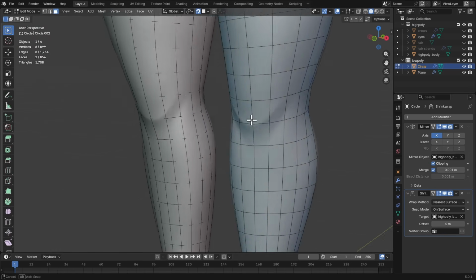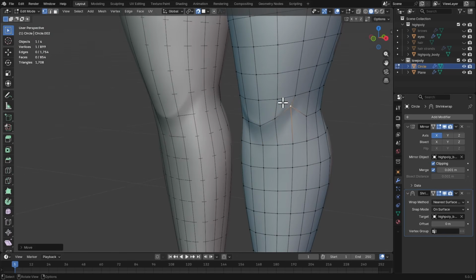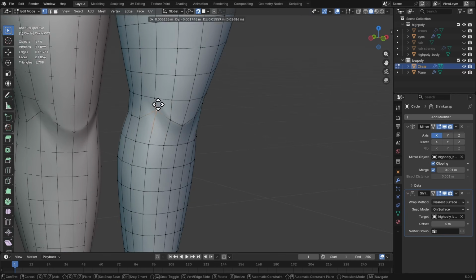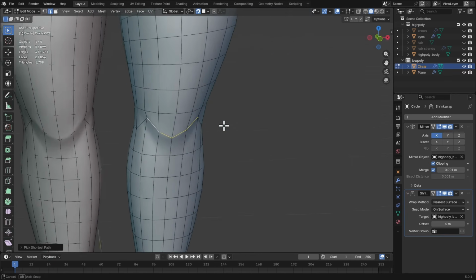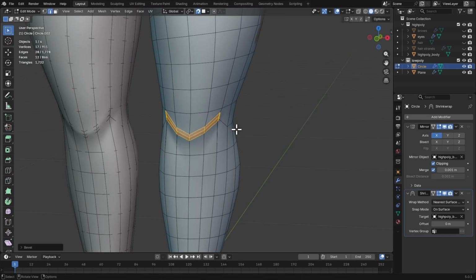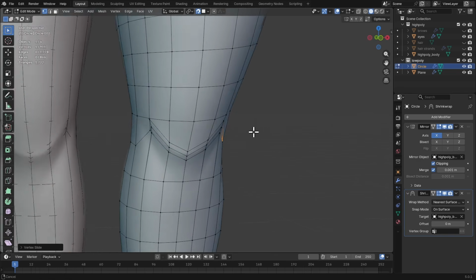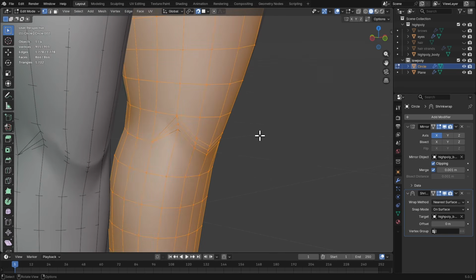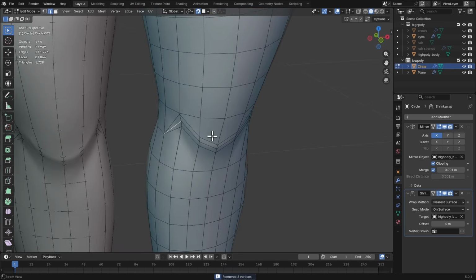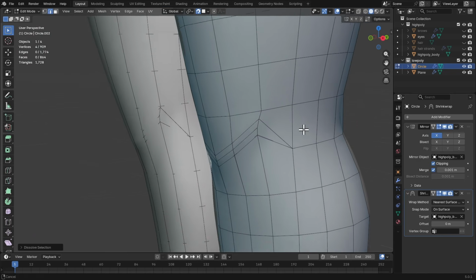So I'm going to go into edit mode, and I'm just going to shift this up a little bit, something that looks like this. Okay, and then I can select this, Control B to bevel this out. Then we can select this vertex, GG, to slide this into here. Also select this one, GG, to slide this into here. A to select all, and M to merge by distance. And now we can select this edge. We don't want triangles. We can select this edge, select this one, Control X to dissolve them.